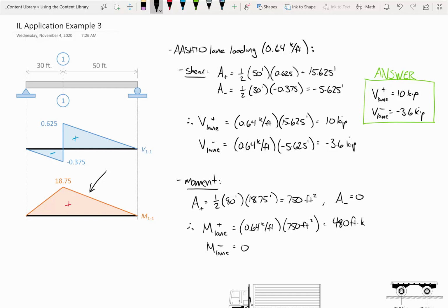Now, what that means from a behavioral perspective is, this is a simply supported beam. Remember, let's go back to the basics of an influence line. I'm taking a single unit load and I'm moving it across the structure. Think about how this structure would deform, how it would bend if you move that load. It's always going to smile. It's always going to produce a smiley face, a bended shape or deflected shape, something like that. There is nowhere that I can place a load on the beam that would cause it to frown. So none of the loads that I place will cause negative moment.